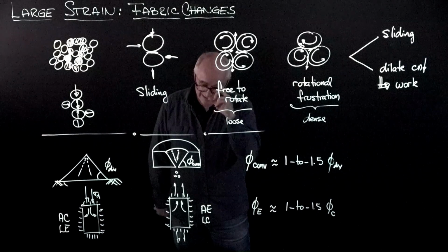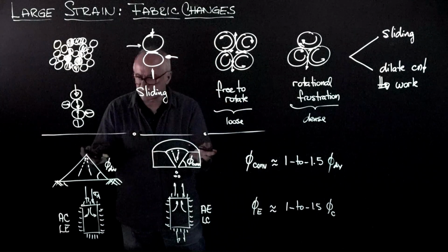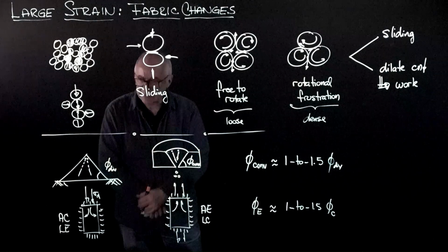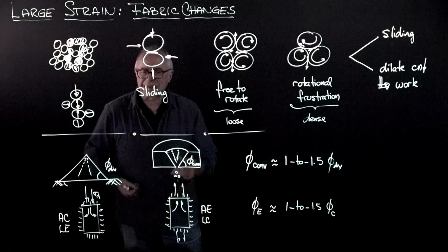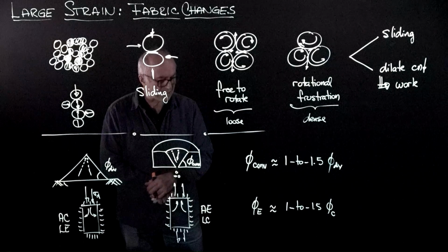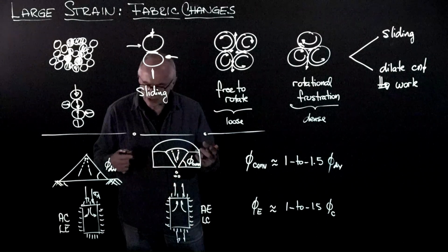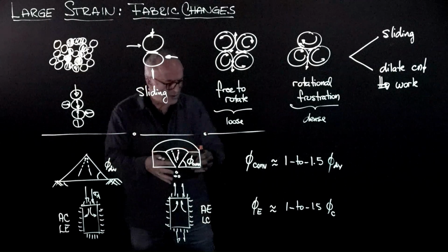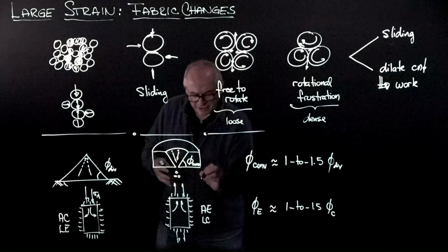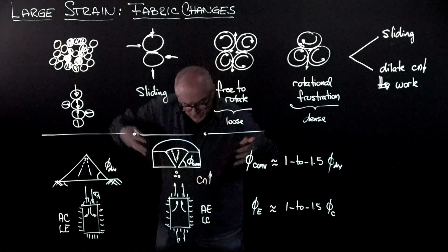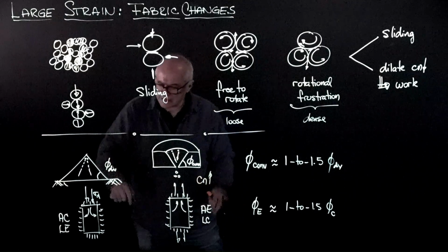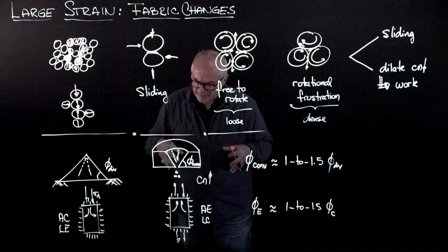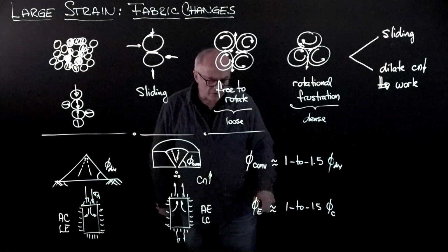This is really quite fascinating. From such a simple experiment of just measuring the angle of repose in these two situations, I get the similar friction angle anisotropy being mobilized. The implications are huge, but one thing that we can conclude is that in convergent flow, the coordination number tends to increase because particles are converging, while this is not the case in divergent flow. It's more complex than that, but it's a matter of particles coming closer together.